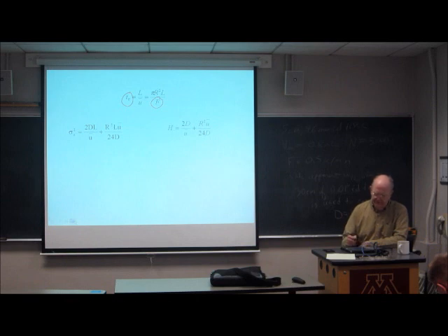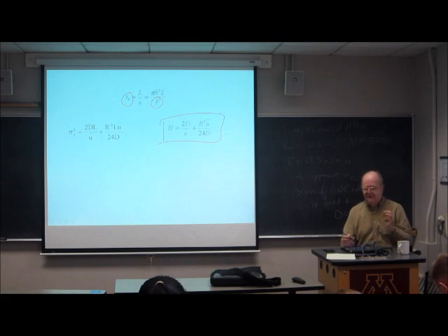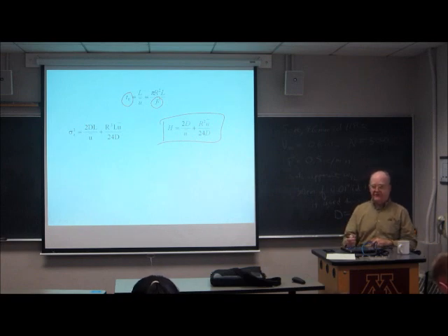And so combining the sigma squared and the t naught squared, we can come up with an equation for the HETP. And it says that the HETP of this tube is 2D over U average plus R squared times U average over 24 times D, the diffusion coefficient.